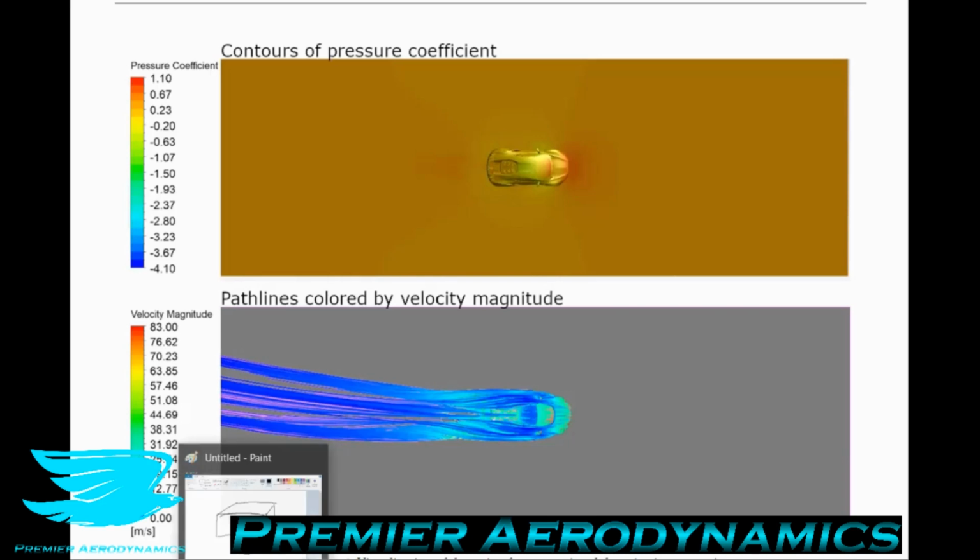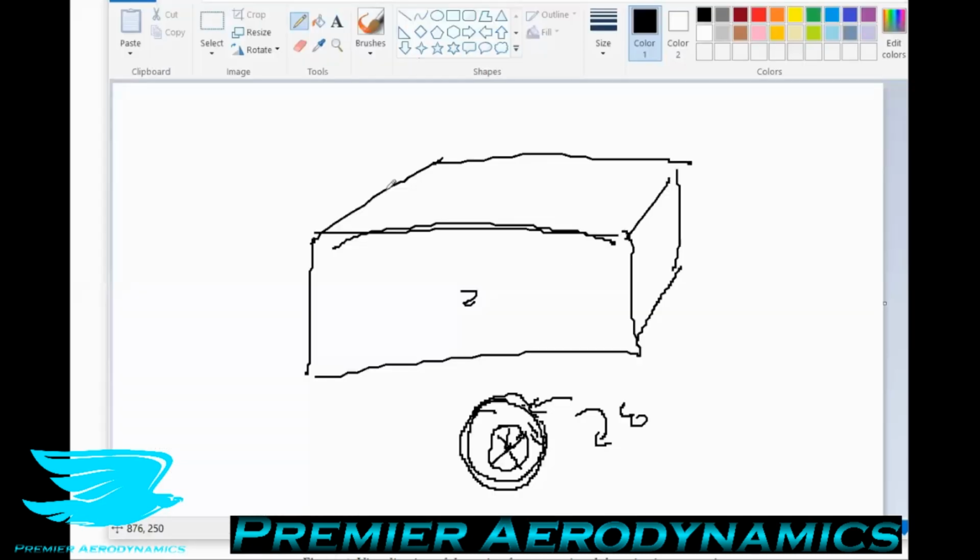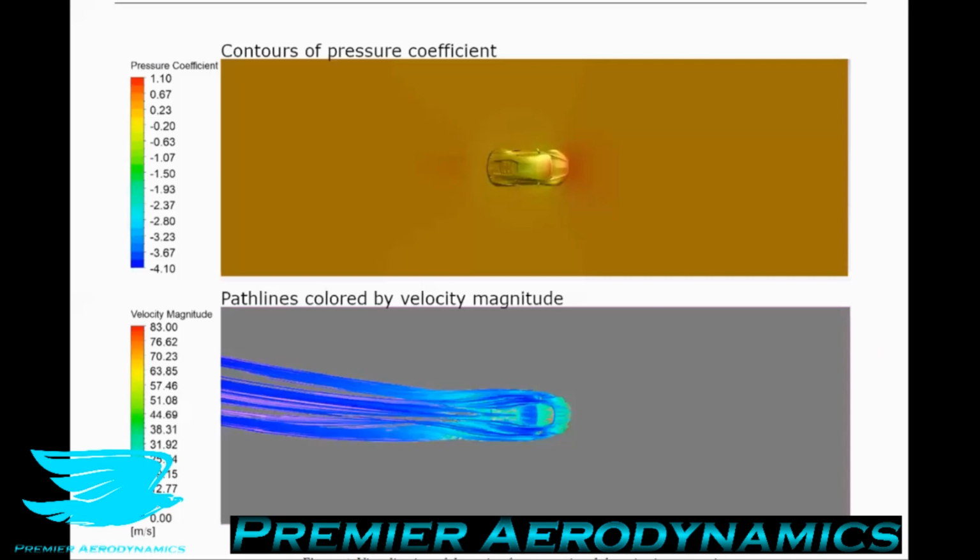What does this mean? So for this square domain, like this rectangular domain with no curved sides, what they're saying is, okay, we're just going to say that there's this kind of motion going along there. And we're going to say all these cells, depending on how far away you are from the center of rotation, has a different tangential velocity moving in this circular motion. So it is quite an ingenious way of using the MRF, and it's quite tricky to get that to work in CFD. So they did quite a nice job here doing that.